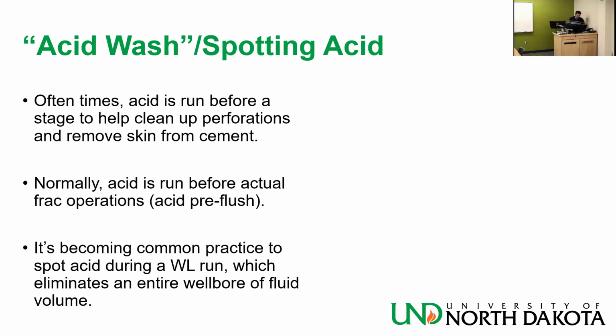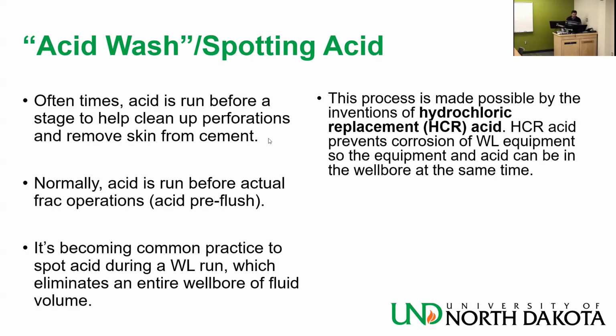It's becoming common practice to spot acid during a wireline run as well, which eliminates the need to fill the entire wellbore with fluid volume. This process is made possible by the invention of hydrochloric replacement acid, HCR. HCR prevents corrosion of wireline equipment, so the equipment and acid can be in the wellbore at the same time.